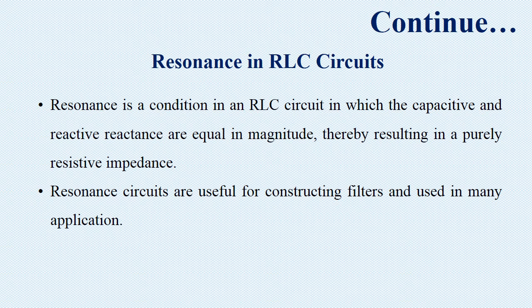And later on, this capacitor will act as a voltage source and it will supply energy back to the inductor. So in this way, energy will be transferred between the capacitor and inductor. The rate of this energy transfer depends upon the values of L and C. Because of this transfer of energy, we will see oscillation in the circuit.